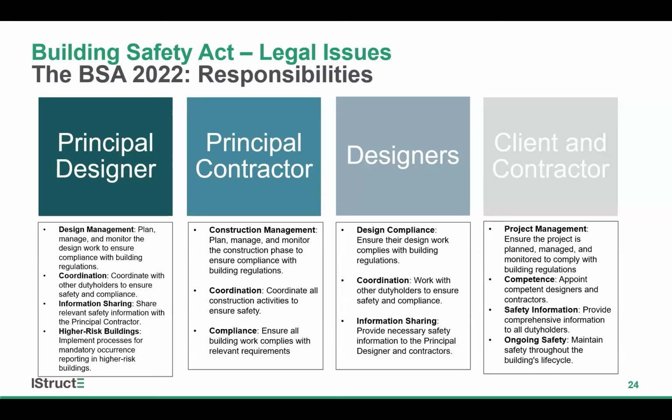So when we're considering higher risk buildings, the client is required to appoint the named principal designer. And of course, this is the important role which involves influencing how risks to health and safety are managed throughout the project. And as recorded on the slide, this will include design management, so the duty to plan, manage, monitor the design works to ensure compliance with building regs and other applicable standards.